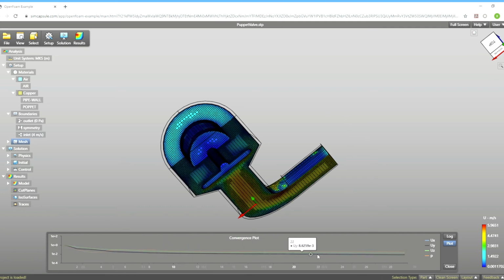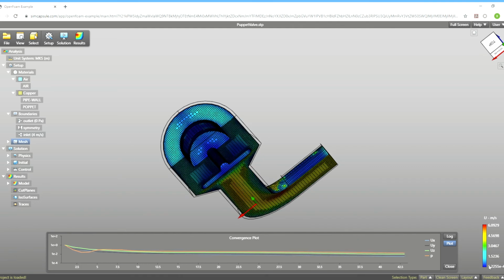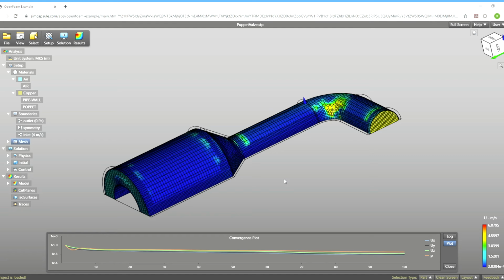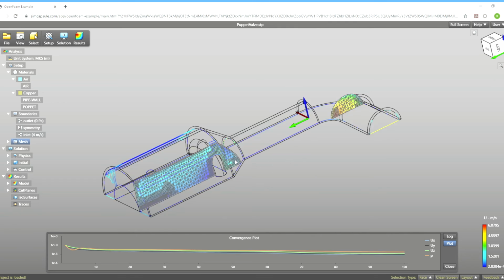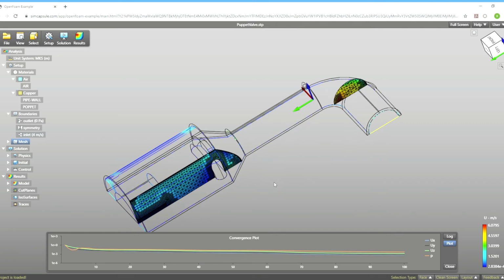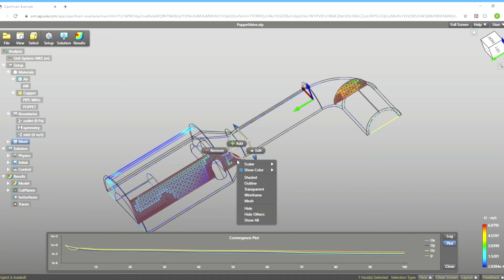Now we come to post-process view. Minima and maxima values on legend bar are updated with the current result. We can add cut plane or any other filter. From context menu, add cut plane. New cut plane initially is located on the center of model bounding box, aligned to X direction. Then we can modify parameters or attributes by edit.